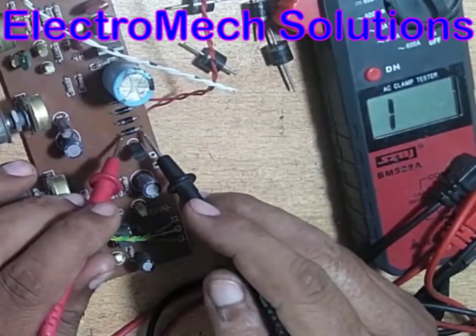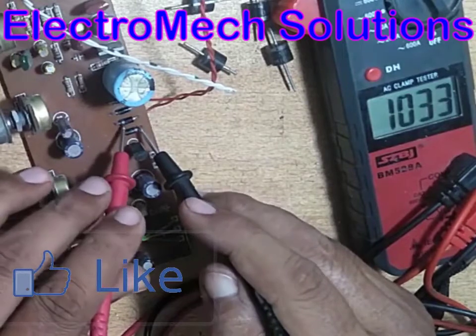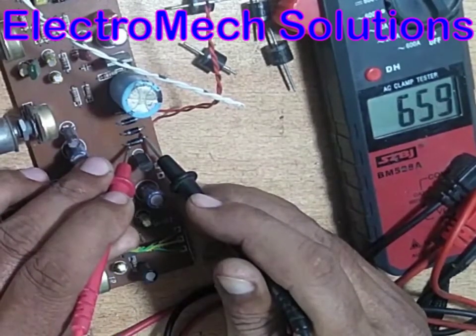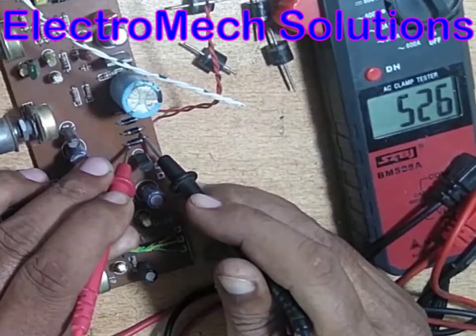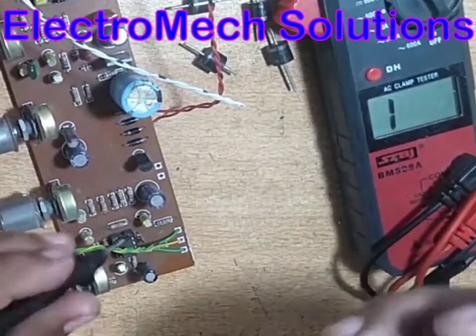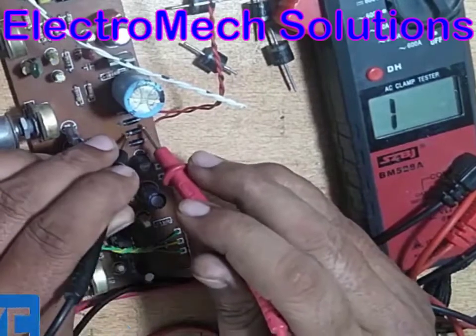So this one is the first diode. This side is negative, this positive, as you can see. When we connect properly, you can see the resistance. This is forward bias, and when we connect it in reverse bias, there will be nothing.